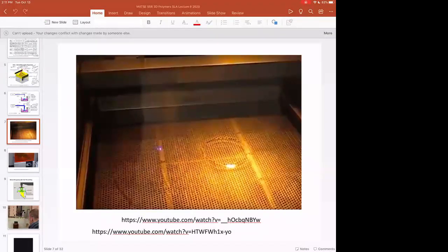Also, because they're reactive chemicals, you just can't put them in a bag. You can't hold these polymer pellets in your hand. The polyethylene is generally pretty non-toxic, other than the dust, of course. But these are reactive chemicals, and so these are a lot more like organic chemistry things that have their own set of hazards, rather than melting plastic, which isn't too bad as long as you don't get it too hot and start smelling all the styrene coming off of ABS or something like that.